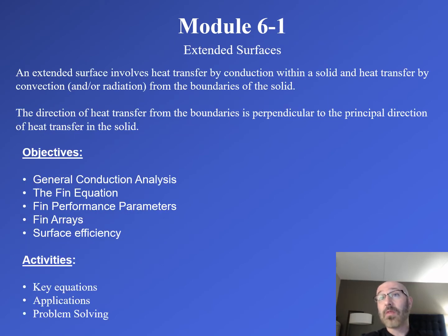So in 6.1, the first section of this module, we're going to concentrate on extended surfaces. An extended surface involves heat transfer by conduction within a solid and heat transfer by convection and irradiation from the boundaries of the solid. The direction of the heat transfer from the boundaries is going to be perpendicular to the principal direction of the heat transfer in the solid.